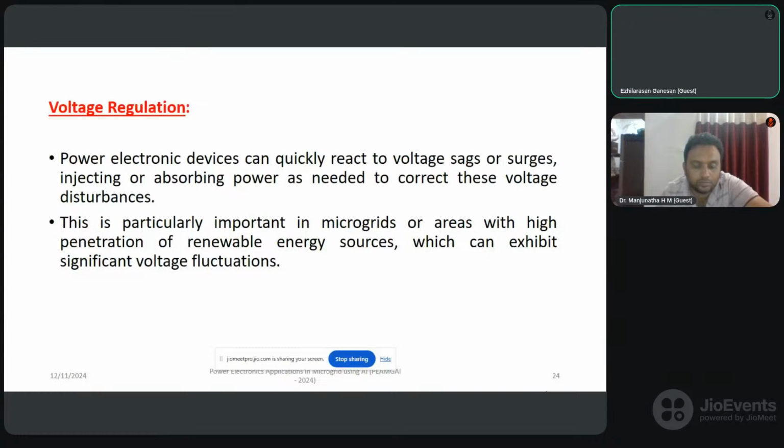Right now, power frequency correction is very easy. It will happen very quickly. So conventional power systems had those type of problems. Similarly, voltage regulation also, we have to adjust the exciter in the alternator in the power station, to increase the voltage. We have to change the flux. All these things now came into very quick control through the power electronic devices.